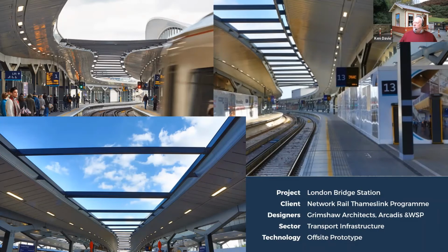Originally, I can't remember how the split was, but some of the lines went all the way through and into central London, whereas others stopped, and the stopping platforms had to be raised so that the number of through platforms could be increased. And to minimise the load, polystyrene void formers were used under the platforms to reduce the mass of concrete. It's possibly a technique that could be used in infrastructure projects where there are concerns about bearing capacity, structural loading capacity. An interesting project all round.